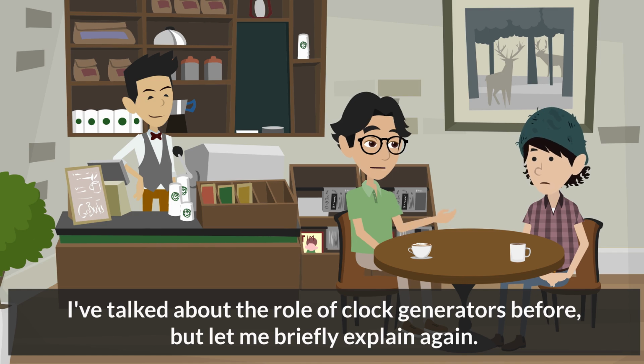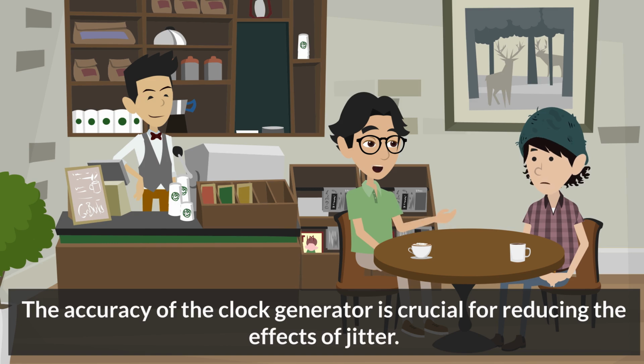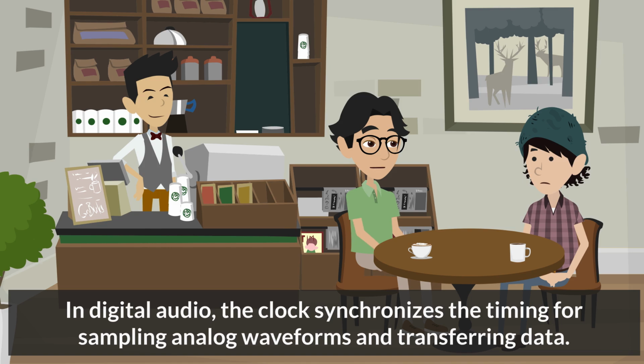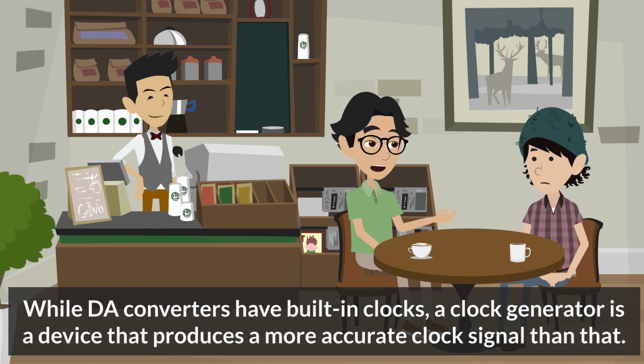I've talked about the role of clock generators before, but let me briefly explain again. A clock generator is a device that establishes the reference timing for digital signal processing. The accuracy of the clock generator is crucial for reducing the effects of jitter. In digital audio, the clock synchronizes the timing for sampling analog waveforms and transferring data. Playback devices extract signals at regular intervals according to the clock and perform DA conversion. While DA converters have built-in clocks, a clock generator is a device that produces a more accurate clock signal than that.